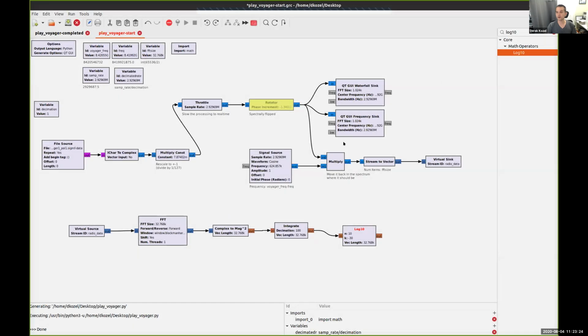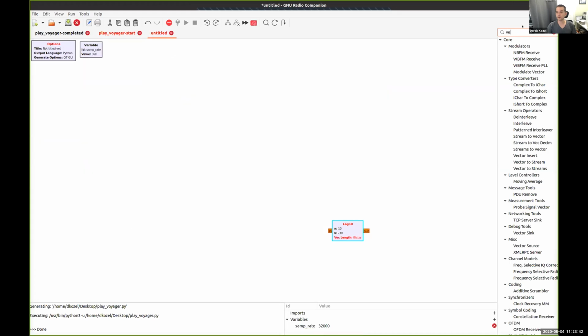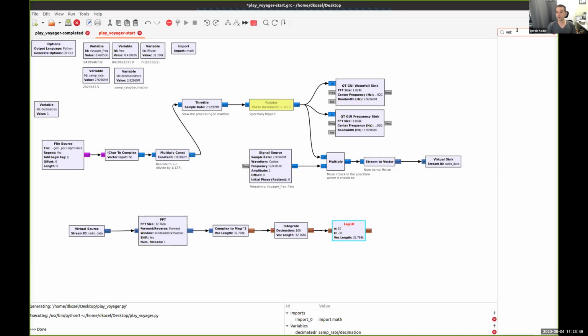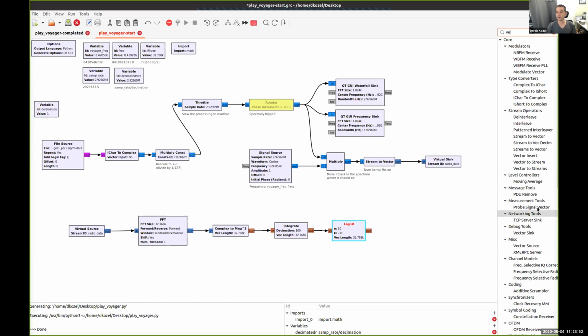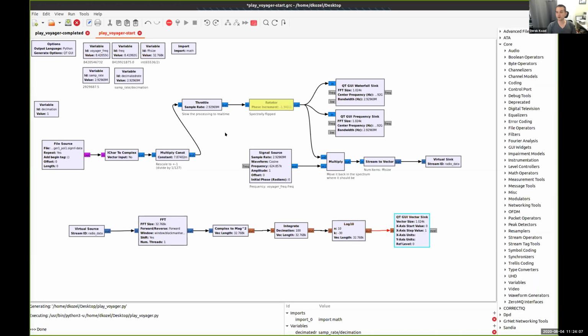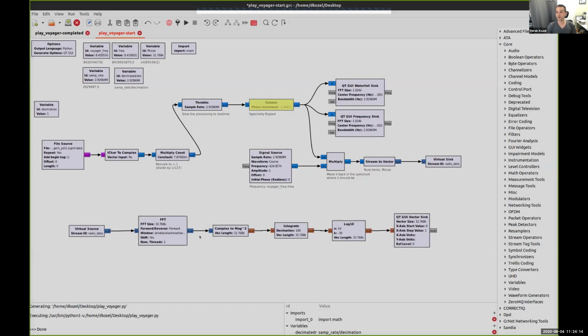And finally, we can view the data. So up above, we were viewing the data with a waterfall sink and a frequency sink. We kind of want to reuse the frequency sink, but we've already done the Fourier transform. So this has that built in. So instead, I have a bug in my version where when I type C, it opens a new flow graph. The block that I've just grabbed is the Qt GUI vector sink, but apparently I can't type vector into there. And so if we do this and update just the vector size one last time, that's the full signal processing connected there.